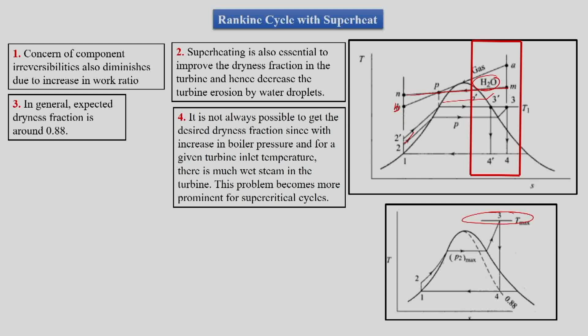Further, it is exposed to high temperature. So the strength of the turbine would reduce in the case of fatigue, and further it is exposed to high temperature. So this becomes a delicate fact to note. So there is a limit due to metallurgical sense for the high temperature to which we can go. There is a limit on this side where we can go.